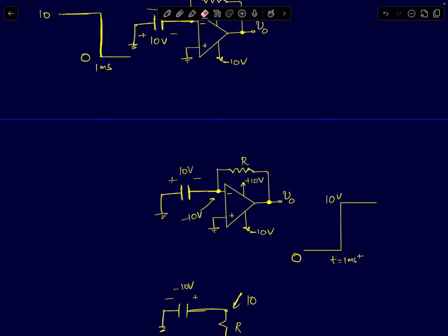And this follows from the fact that the capacitor voltage cannot change instantaneously. Suddenly you have grounded one plate. So what will happen to the voltage at the other plate? It will go to minus 10 volts, so that the total voltage across the cap is plus 10 volts. So Vx suddenly drops from 0. It was at 0 for a long time. It dropped to minus 10 volts.